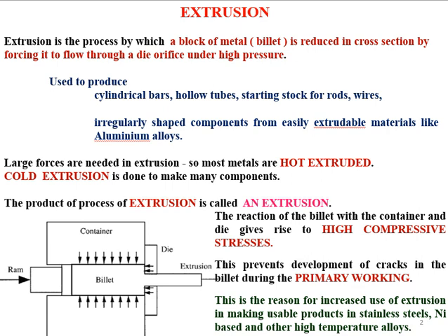Right? So compared to other metal forming processes, the forces and the stresses that we require in extrusion are extremely high. In the case of extrusion, we apply stress from all directions. In the case of rolling, we were applying the load in a specific direction perpendicular to the rolling direction. However, in the case of extrusion, when we apply force onto this billet using that specific construction, the confined space will equally impart a reaction force onto this material.